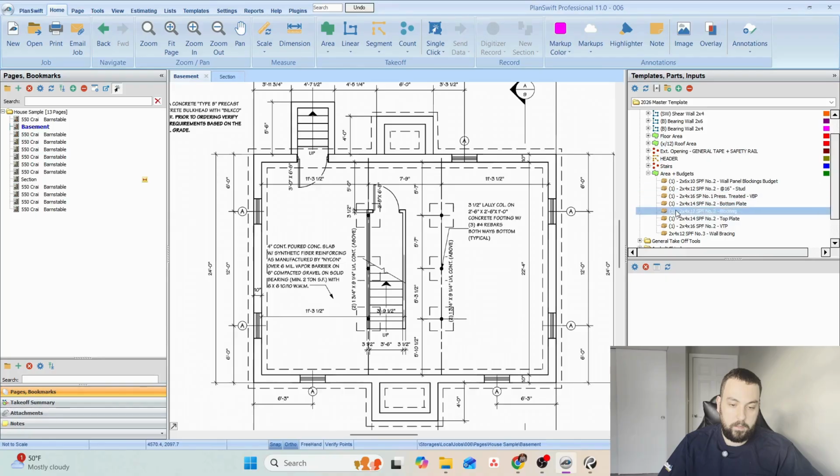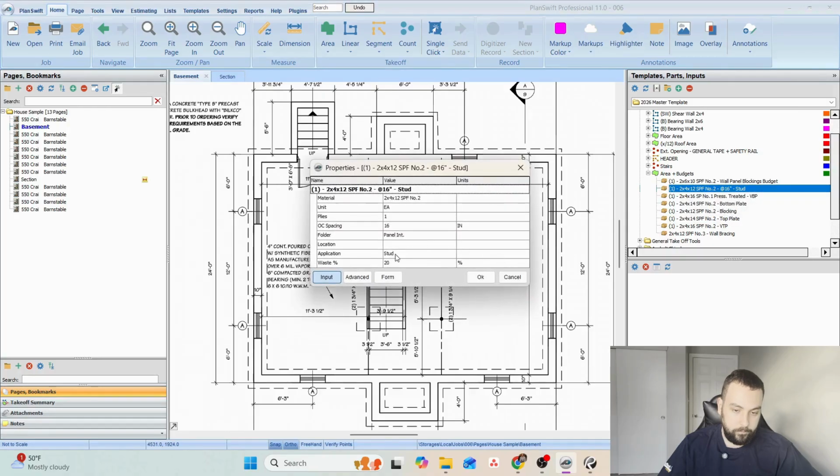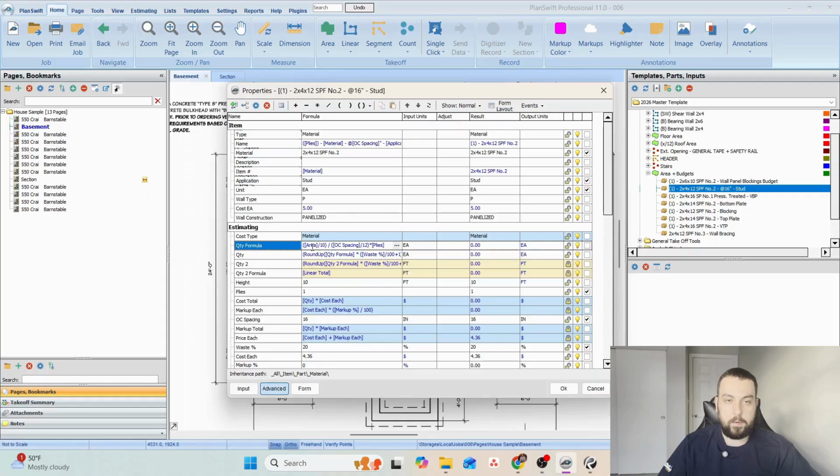So basically, if you remember, walls are linear, based on lines, linear footage. Instead of linear footage, you see area divided by 10. In my experience, I saw an average between 90 and 120, 110 linear footage for every 1,000 square footage of partitions. So at every 1,000 square feet, I have 100 feet of walls. So 100 divided by 1,000 is like a factor of 10, for 10.